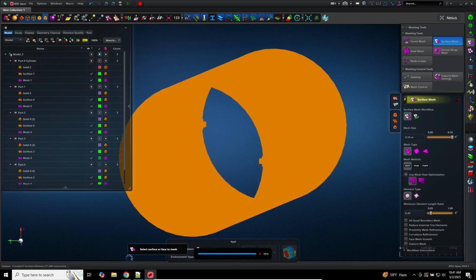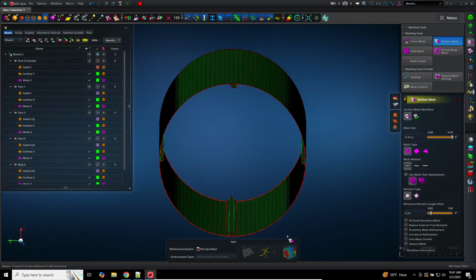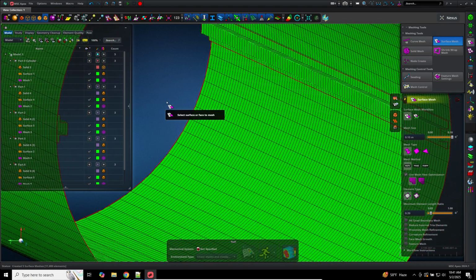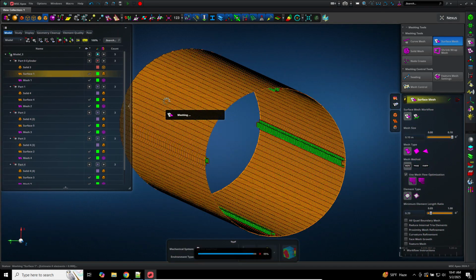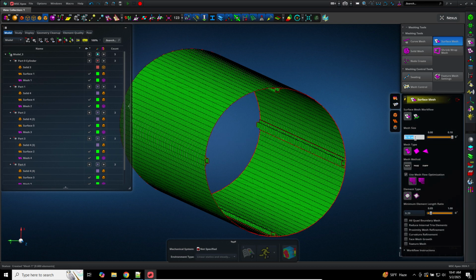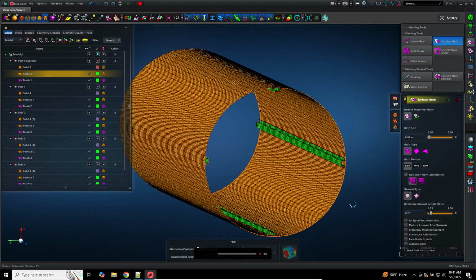I'll leave it up to your judgment to decide what element size to use. Now, again, I'm assuming you're a beginner, so I'm going to use a very large element size. This is sometimes called a very coarse element mesh. If you want something that is a fine mesh, you would use a smaller element size, and then you'll notice that your mesh is more fine. The elements are smaller. Here, we're not aiming for a very detailed, or rather very fine mesh.